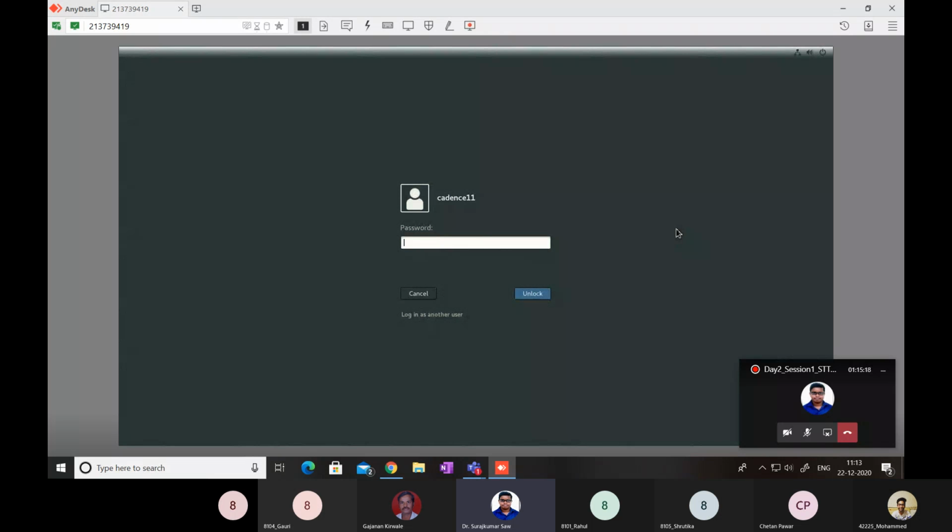Now we'll provide the period. Don't put 100 nanoseconds, because if you provide the same period, you cannot differentiate the output. You need to change the period. We have given 160 nanoseconds, let's say. Whatever you want, you can put. I have given 160 nanoseconds. Rise time and fall time I keep the same. Delay also the same. Now you should tell me how much I put the pulse width.